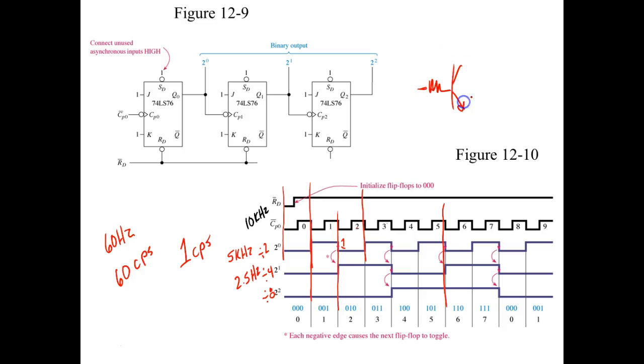I came in with this little circuit right here. You remember this guy? First lab, wasn't it? Or second lab. So I brought Alabama Power in right here at 60 cycles per second, but this is analog. I ran it through this switch and converted it to digital. I ran this into my counters, and I had the circuit hooked up counting in seconds.